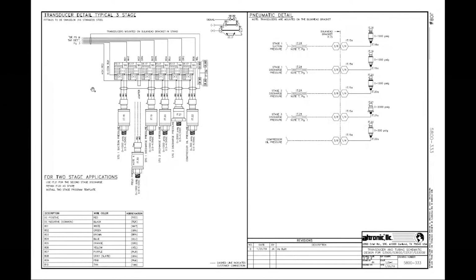I showed you a version earlier where it was a physical bird's eye view looking down at the top of a 3-level terminal block. Now, to add to confusion, when we get to this page, we draw it out just a little bit different, but understand that the side view of the terminal block is just like this. So the lower level ties from one side to the other, the middle level ties from one side to the other, and the top does the same.